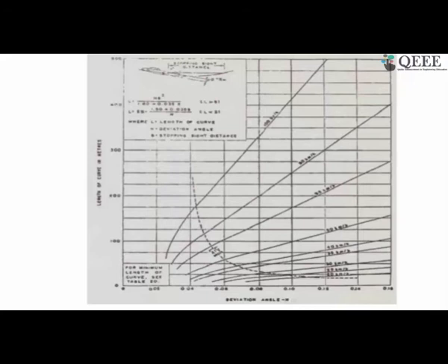In mountainous terrain, both types of curves are going to be there. Another question I received: if we provide small trees on the median of a valley curve to prevent the glare of headlights, then is there no need to calculate the length of the valley curve for headlight sight distance? The headlight sight distance is not for the glare from the opposite side.